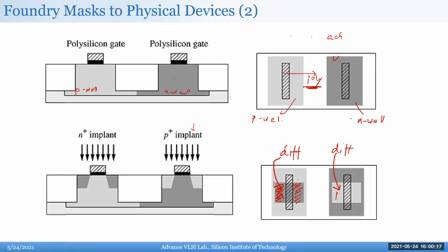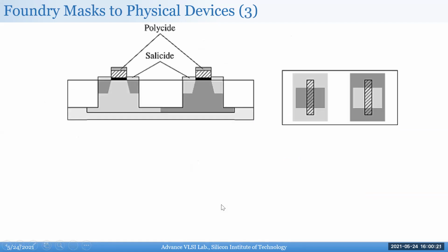Okay, so looks like people are slowly getting it. And this is the salicide process which I was talking about. Oh, actually, Prajita, I think I was mistaken. Yeah, that's true. In a lot of processes, for salicide, I said you use the poly mask. Actually, it is the diffusion mask because they want the source and drain to be pretty conductive as well. But this is not for all processes. Like 130 nanometer plus, the saliciding is done for poly only.